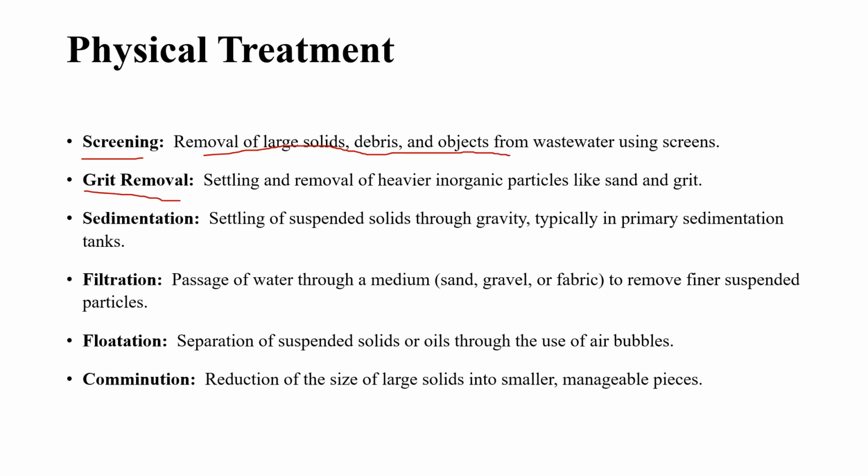The second one is grit removal. Again, it is a removal of solids, but of heavier inorganic particles. We can see these particles with our eyes, but we can't remove them with screening, because when you use screening to remove inorganic particles, they will collide with each other and disturb the screening process.